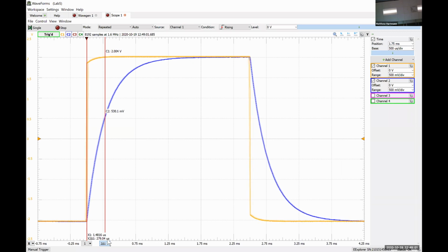Anybody get a number? So we know tau, we know R. Okay, 2.832 times 10 to the negative 7. So I got it as 283.3 with some rounding in there, nanofarads, 10 to the minus 9, because I work in units of nanofarads, microfarads, etc.